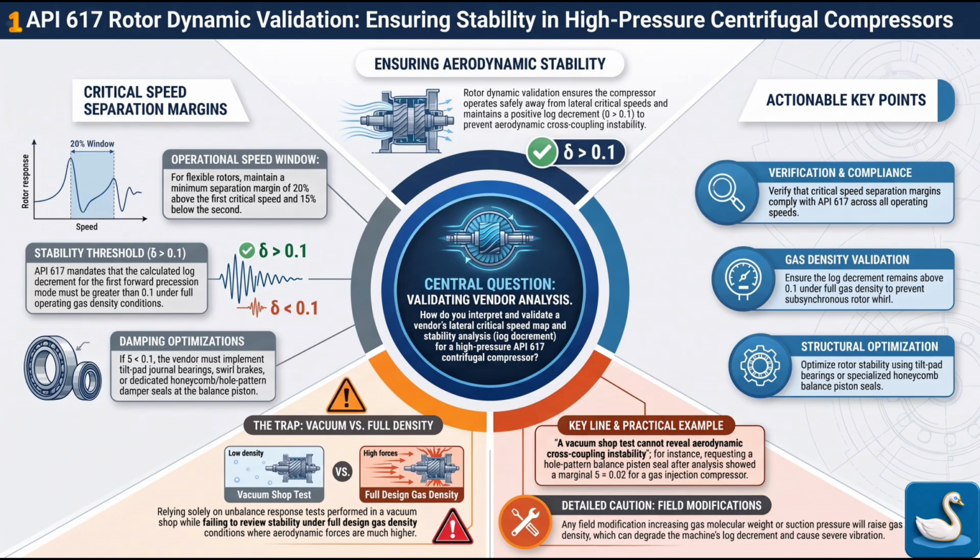So think of log decrement exactly like the shock absorbers on your car. If you have a healthy positive number, say well over 0.1, it means when you hit a bump, the car bounces once, the shock absorber dampens the energy, and the chassis settles immediately.